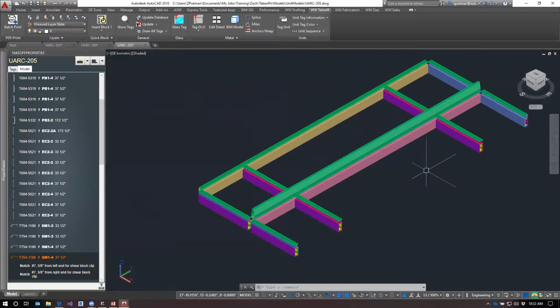You almost never have to save this drawing because a lot of times the workflow is make some data changes or tagline changes, run UPD, run BIM, QBIM, do some more stuff, find more changes that you need to make, close this without saving, make your data changes, UPD, QBIM, do some more stuff, make more changes, UPD, QBIM. Like it's that kind of cycle.